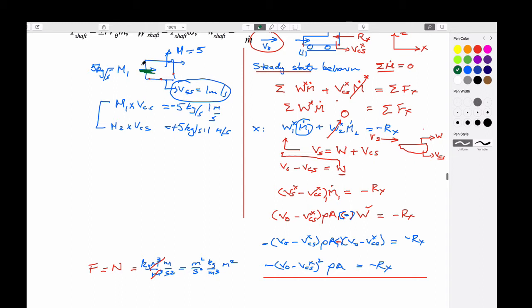If it's a static control volume, it's the same as the water going in. But if it's moving, it's not necessarily the same. So W is the water speed coming out of the hose on the boat. V is the velocity of the boat. If you're standing on the quay watching both of them, the velocity of the water coming out of the hose plus the velocity of the boat is what you see, which is this.